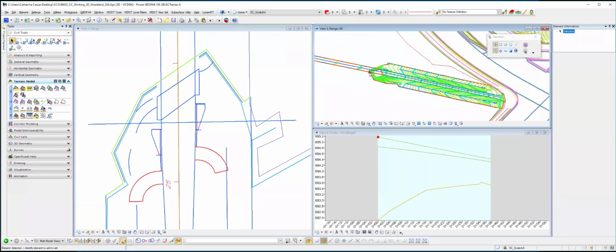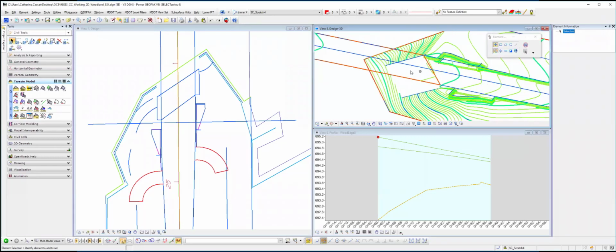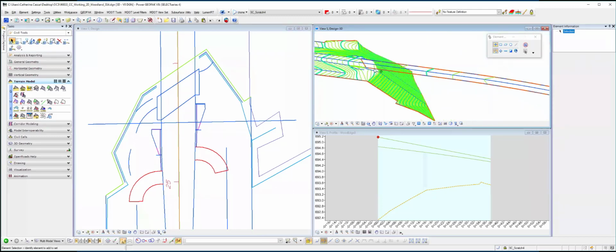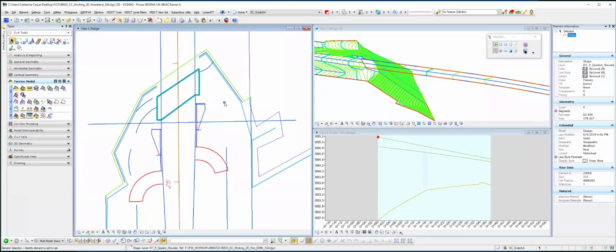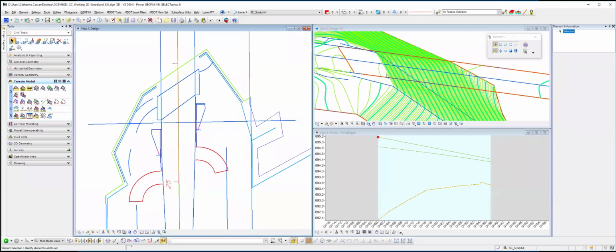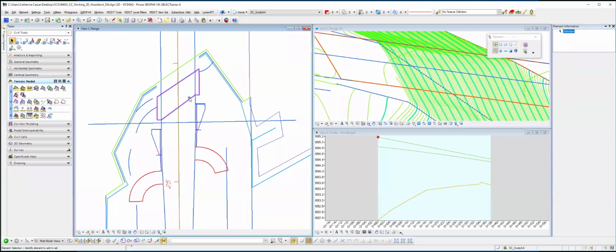Right there. See it? This was actually part of the structure. The wing wall, the walls and stuff were going to be here. Right. And part of the underneath. So any flat shape. This shape here has no elevation to it whatsoever. This is just in 2D view. It's flat, no elevation at all, and you can still use that as a clipping boundary, essentially, to create a void. So I just used a drape void in this case,